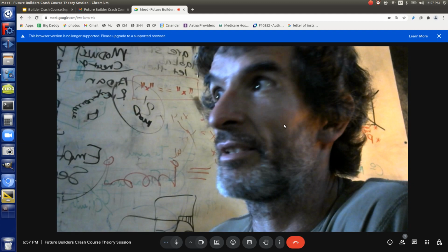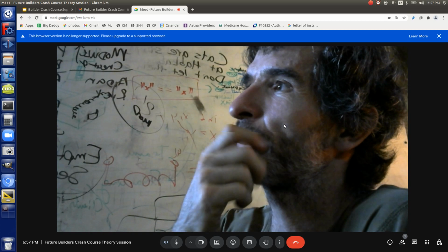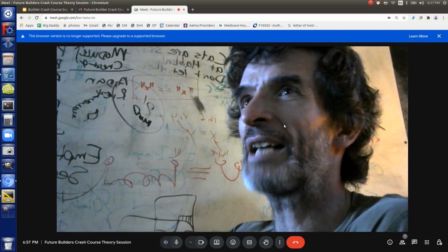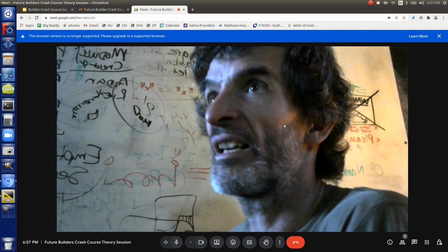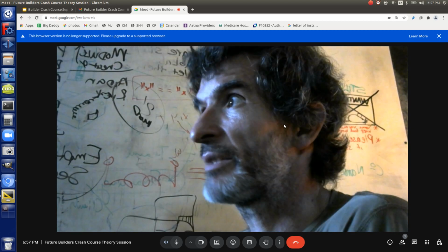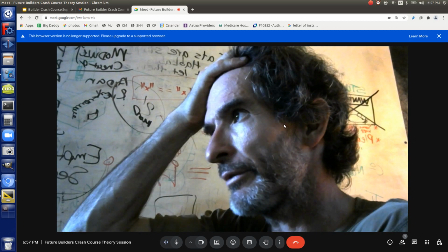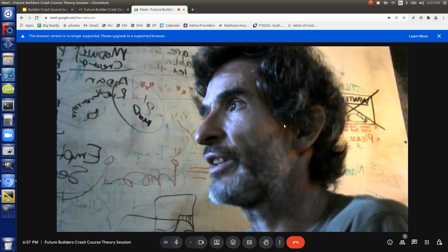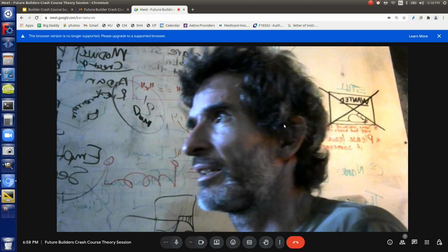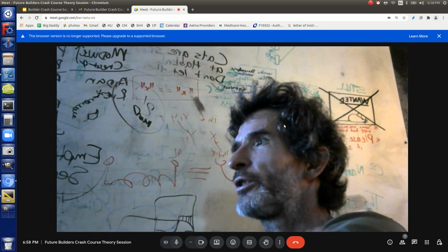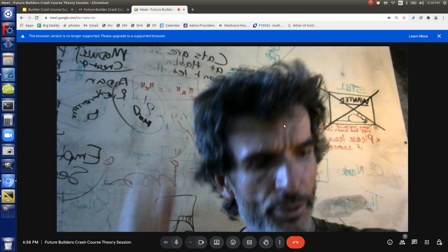So you're already looking at, okay, I know from first principles that a nail maxes out at 1,000 if it was 100,000 psi or so. Rough orders of magnitude. So 100, yes, that makes sense. But if you got like 40 of those nails on your OSB truss, that's like 4,000 pounds of holding force. Hey, that's pretty good. You know that OSB is not coming out. What if you went every 12 inches? Okay, 2,000 pounds. What about every 2 feet? That's 1,000 pounds. Oh, that's getting down there. But yeah, you can start looking at your nail schedules, and you can actually calculate how many nails you need and so forth. So it's useful to have those first principle notions behind you.